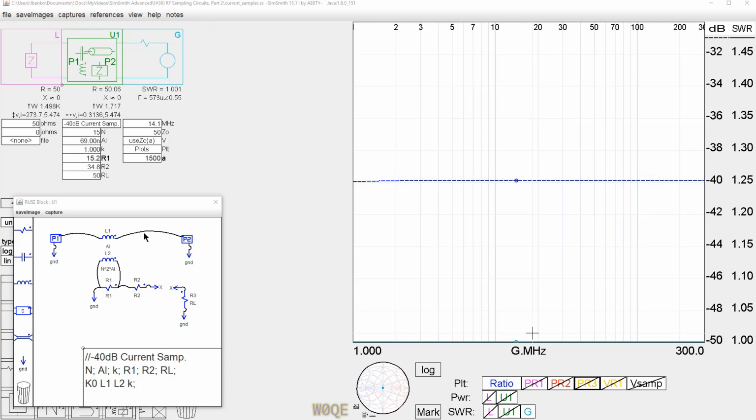And the impedance that the line sees here is the inductance of one turn, which is A sub L, in parallel with this impedance in parallel with those 2 impedances added up. So it's the 15 ohms in parallel with 84.8 divided by the turns ratio squared, and that's the basic way it works. However, there's a lot more to the circuit than that, but let's just keep going for a moment.